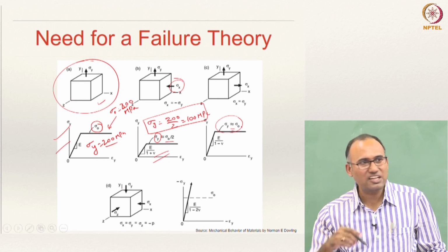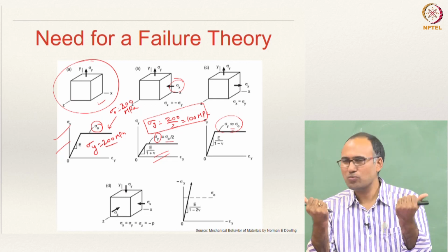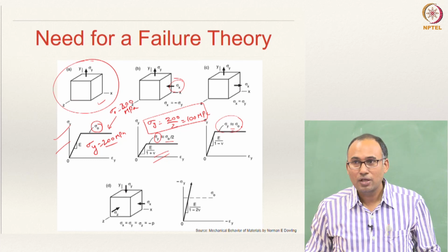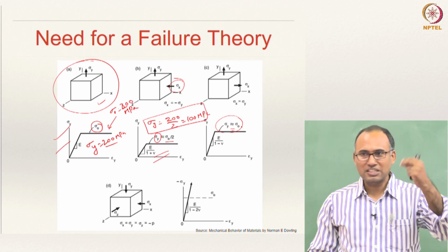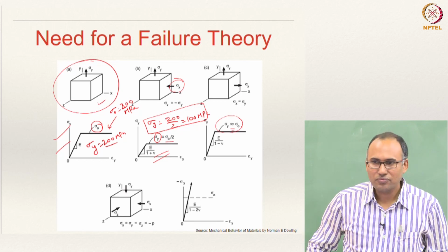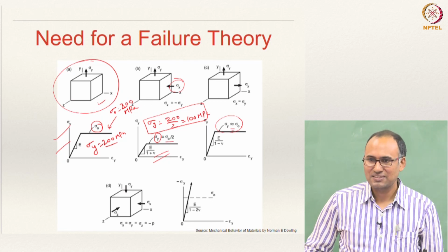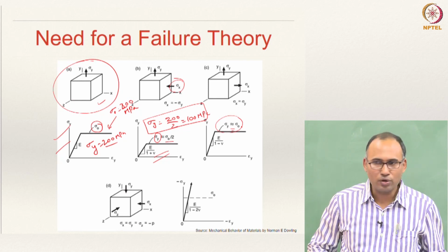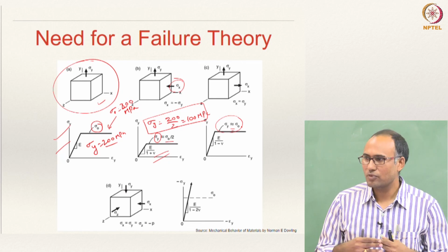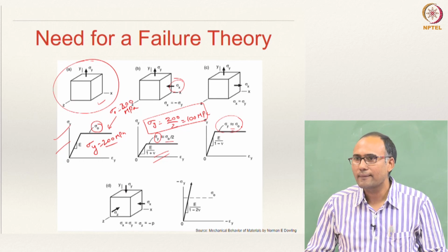It is not significantly dependent on the lateral load. Very small effect. Experimentally, it can be shown that. If you do the experiment, that is what you will observe. So, if you have a non-uniaxial loading in the material, to define failure is not obvious. Just by changing the direction of the loading, you are not able to make sense of the nature of the failure, right? What stress leads to failure and so on.